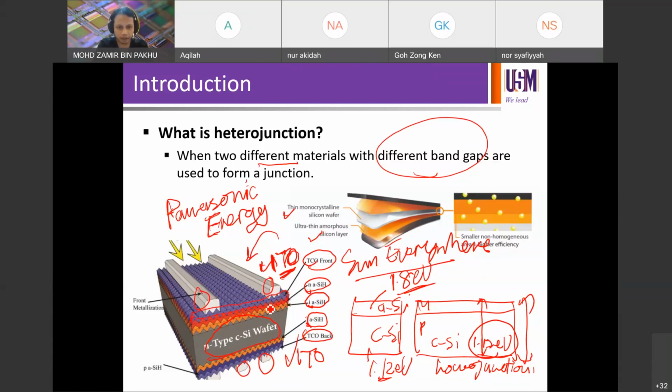So the electron extraction and the hole extraction is done in this layer, laterally, meaning along the thickness of the TCO, within the channel. So it's called lateral conduction. They still have front metal contact and rear metal contact in order to improve the carrier extraction possibility, or the carrier collection we discussed last time. Remember the EQE, quantum efficiency and so on. So this is a real life example of a heterojunction device.